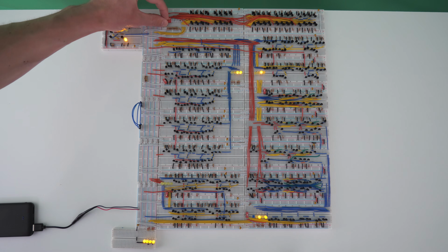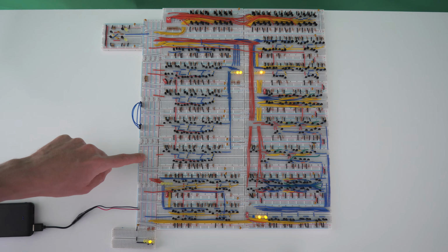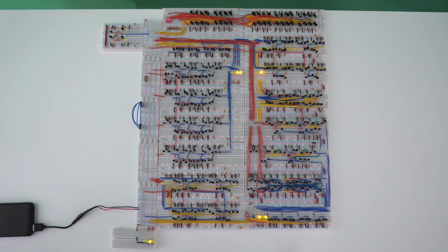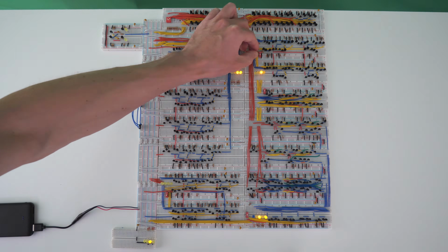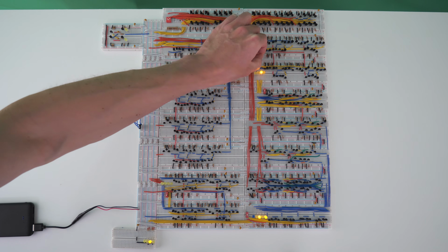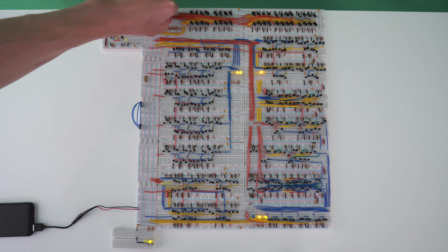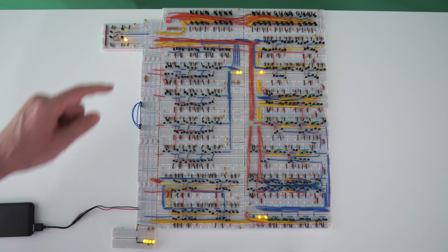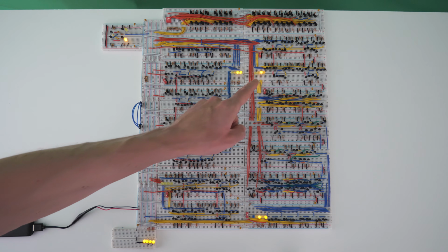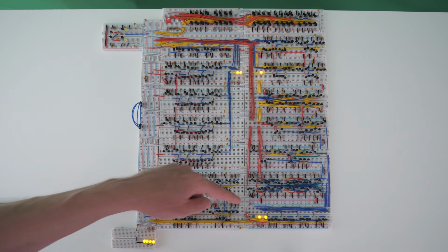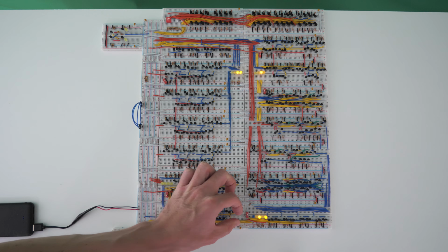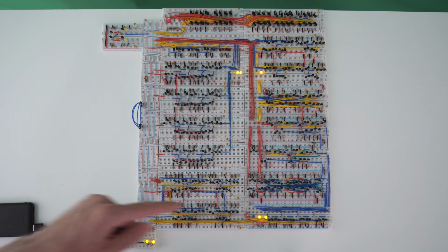So we will send the value of 2 to the data bus, and we will load it into the A register. This is kind of redundant because it's already there. And then we will turn off the memory from being sent to the data bus. And now we have a value of 3 plus 2 equals 5. And we're going to send this value of 5 to the data bus by enabling these tri-state buffers.